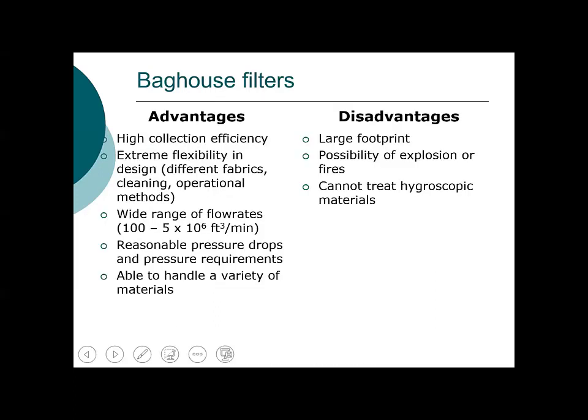The advantage of a baghouse filter, and if you don't mind, I've only got a slide or so and we can finish this. The advantages are high collection efficiency. These are extremely efficient, as I mentioned, up to 99.99% efficient. They're very flexible. You can use different fabrics, different cleaning mechanisms, and you can operate these sometimes inside out or outside in.